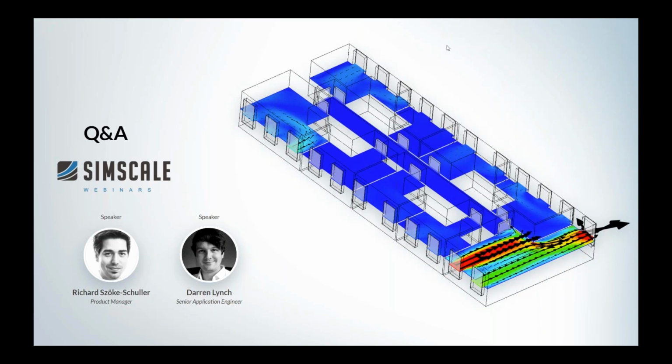Absolutely. Great. So the next one is, does the study have to be done for different wind directions? So I would actually advise, yes, it would be wise to take a few scenarios that you know would be the most dominant wind flows and assess each of those for natural ventilation. In this case, we had one very clear dominant wind direction, which of course we used along with a typical summer wind speed.